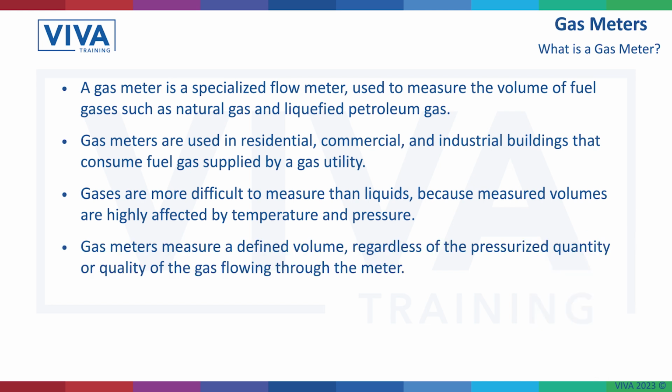A gas meter measures defined volume regardless of the pressure and quantity or the quality of the gas that's flowing through the meter. As we said in the previous presentation, we import gas from all over the world, and some of that gas hasn't quite got the same calorific value as other gas, so you don't get as big a bang for your buck.